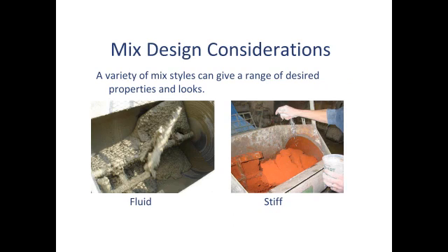Now, I've been talking about fluidity as if that's the only kind of concrete mix you want to be making. And on the left side of the photo is one of my fluid mixes that's an aggregate-based mix. And you could think of it as the closest thing to a conventional concrete mix design that I use. Very fluid, very pourable. But sometimes you want to make a really stiff mix. Maybe you want it to be stiff because you want to pack it vertically up surfaces, or you want to variegate it or hand press it, or whatever name you want to give that